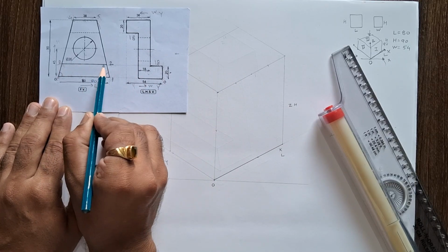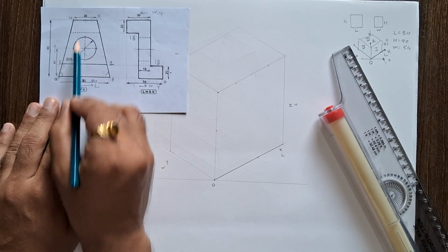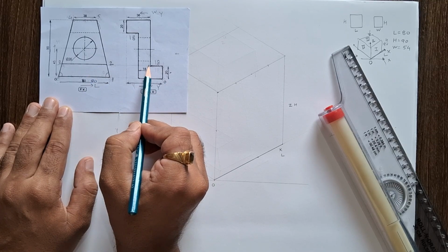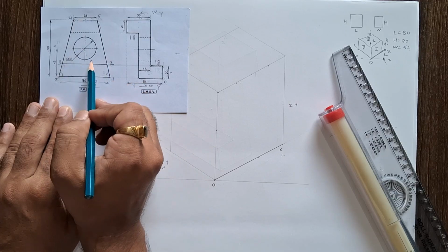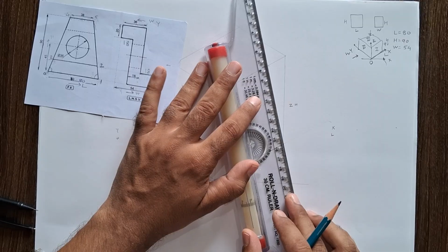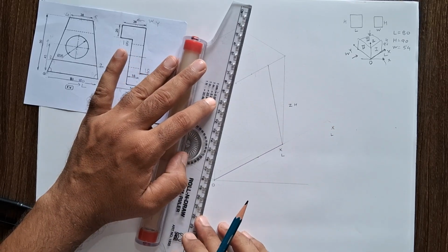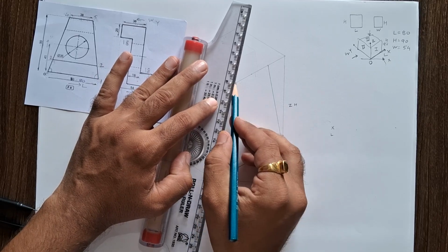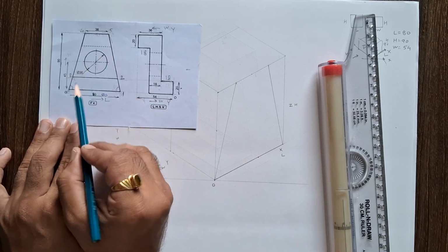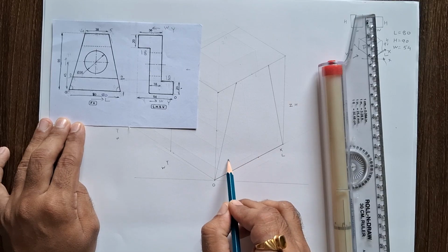This 2-3 edge height is given 20 mm, but this angle is not given. But you can see this profile, this nozzle profile is at the front and also at the back. We are seeing the projection of the same profile here. So even without marking points 5 and 4, we can directly find this slant edge by using thin line. Now you can see by using thin line we have drawn this profile, but this O123 profile appeared here or it is visible here.